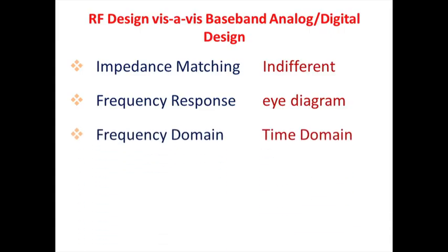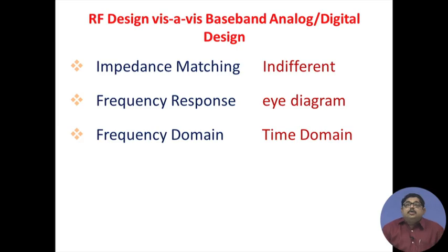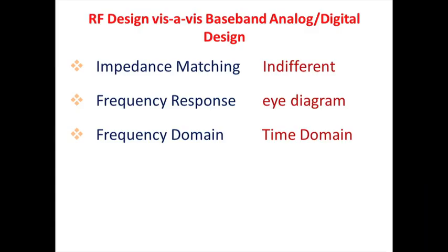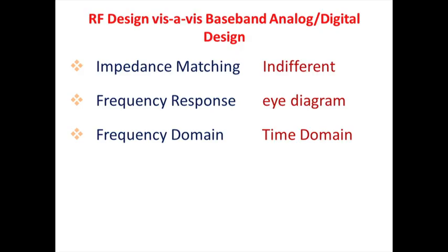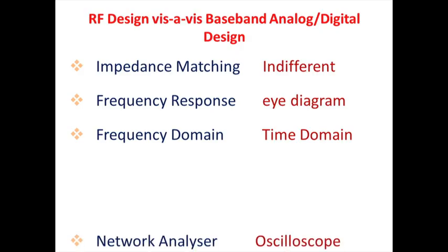Then generally it is seen that digital circuits, etc., talk of the time domain, whereas it is apparent that more concentration is given in RF design to the frequency domain. One of the reasons also is that those very short pulse type of signals like impulse signals, etc., previously RF circuits were not able to pass, but nowadays this distinction is coming down. Also in the time domain there is a lot of microwave technology coming up, but whatever exists in the frequency domain is a useful thing for RF design.